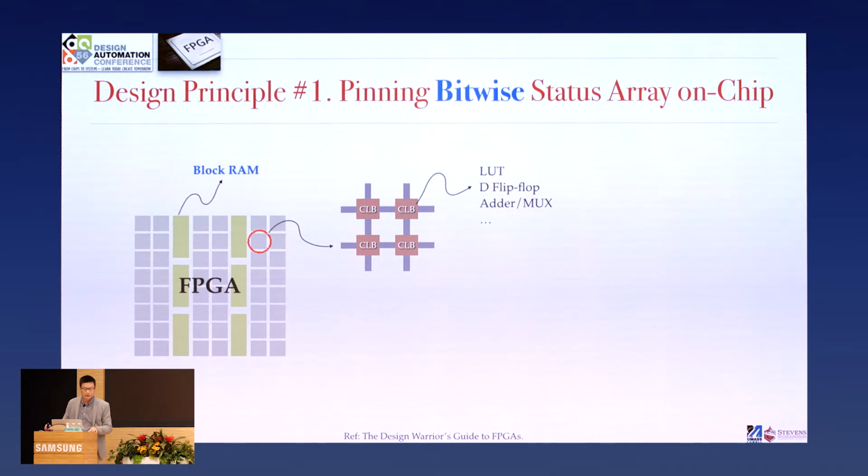It's very nicely laid out together like a wall over there. You have 3 components. First is the CLB, or configurable logic block. You have LUTs, D flip-flops, adders and multiplexers for you to do those arithmetic or logical component designs. And those green ones are block RAM, the on-chip scratchpad. It's very fast. And also there are those things that I didn't draw out here, but they take the majority of the space. That's the interconnect between those square blocks and those block RAMs, right?